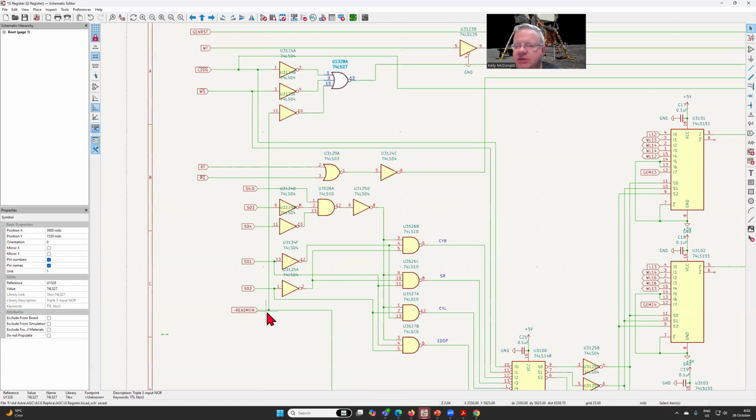Like I said, the one thing I'll probably be looking at a little further when I start debugging some of this is the control sequences, where we look at the actual instruction and sub-instruction and how it generates the control pulses. Clearly the read mem should be at certain time cycles, and I want to see if they conflict with the WG signal as well. Because I definitely want to make sure we don't have a collision between pulling contents from memory to write into the G register versus the write line commands, when we want to write contents from our write lines into the G buffer. So that's something I'll probably be looking at this week, and we can report back on that in our next episode.